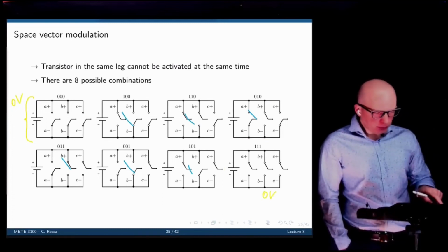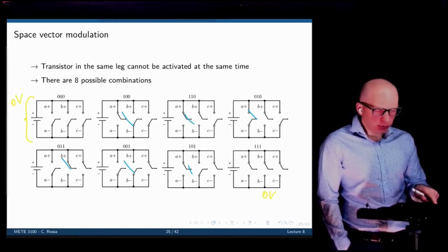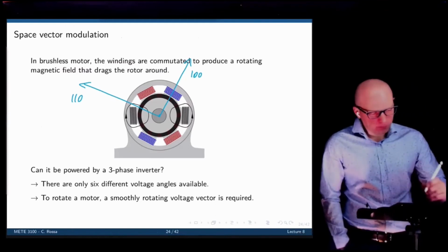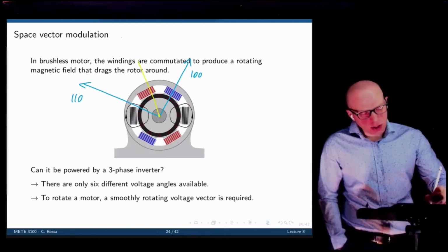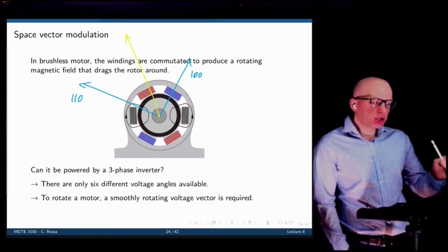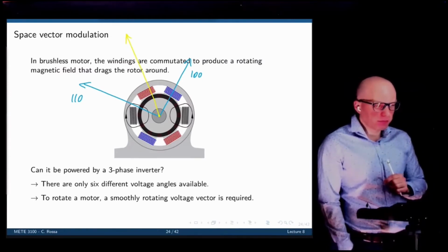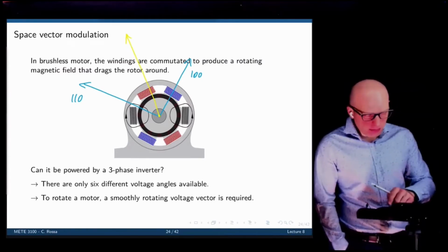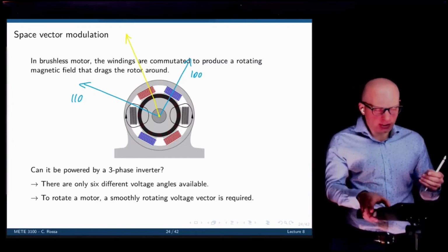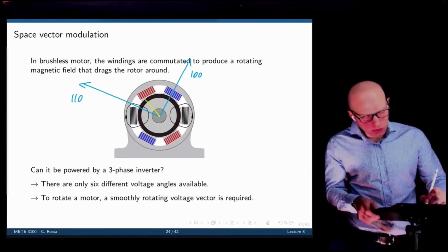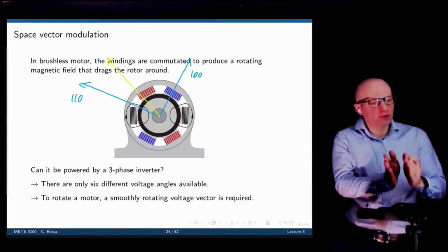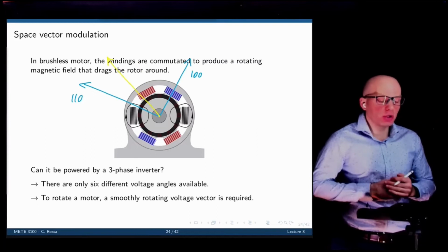Let's say we are working with these two vectors, 1, 1, 0 and 1, 0, 0. I can get any linear combination of these vectors by changing the duty cycle that each of these modes operates at. If my duty cycle goes between 0.3 on one side and 0.7 on the other, then the average resulting vector will shift and now point more towards 1, 1, 0.